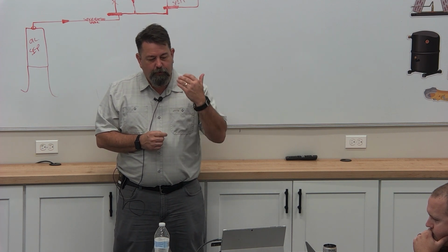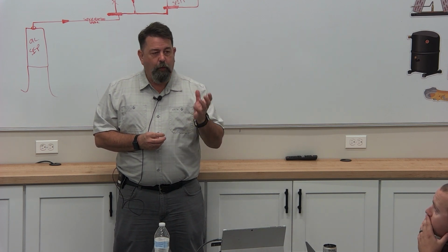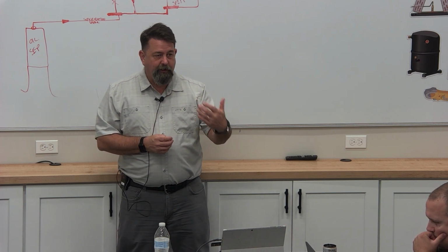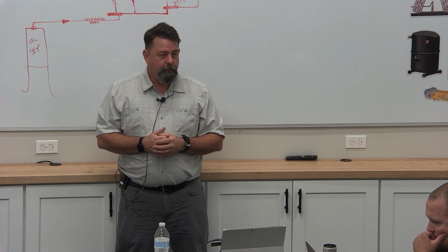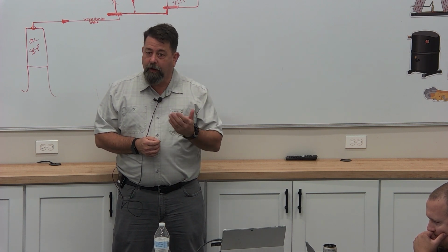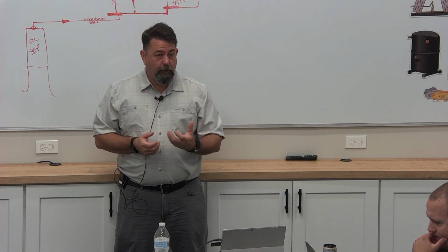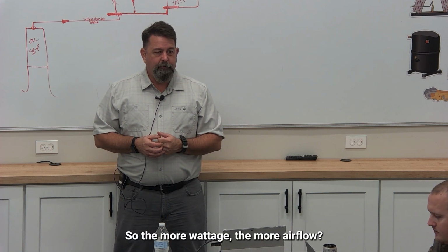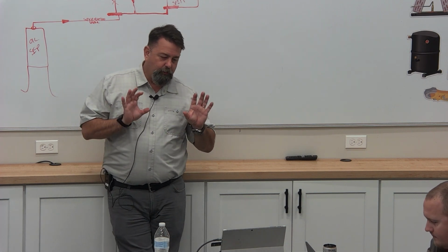If we have to go back with a generic motor, that's okay. It will match the amp draw of that blade and deliver the same amount of air. If I change the blade, that is not true at all. I can definitely push more air accidentally or less, right? So the blade will determine how many watts the motor is actually going to burn. That's what's going to decide that. Now, more pitch, more airflow? To an extent, yeah.